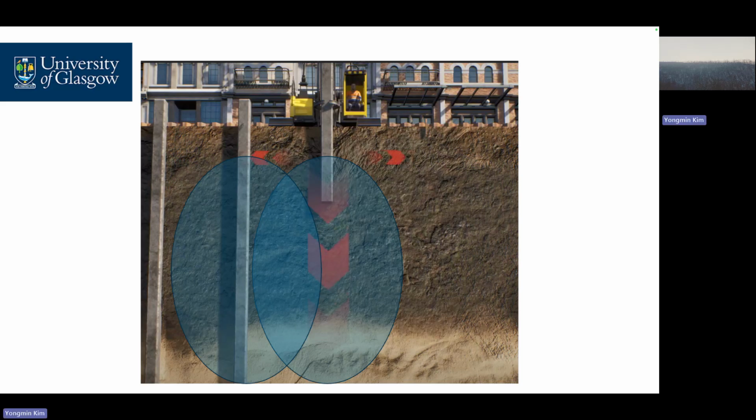And then when it comes to clay, and you keep driving your piles, excess water pressure will probably be generated. Right? Higher excess pore pressure means lower effective stress. Low effective stress means low shear strength. Sometimes hammering is good for soil, sometimes quite negative for soil.